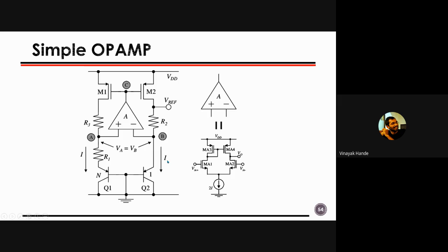So whatever we do for stabilizing the two stage amplifier, we have to do a similar kind of thing to stabilize this band gap based voltage reference, connecting the heavy value capacitor and all. So while designing a band gap based voltage reference, don't go for fancy op amps, because otherwise you'll get into the trouble of stabilizing your band gap based voltage reference.